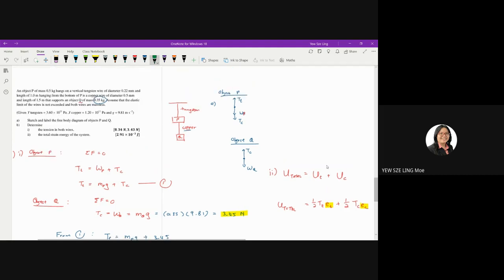Well, for elongations I have two equations. One is epsilon equals e over L naught, and another one is Y equals FL over AE, right? So obviously, I cannot use the first equation because I don't have the strain of the wire. So this one is out, which means I can try to use the Young modulus equation to determine the value of e. So do I have enough information? Well, yes, I do have Y. I'm given the Young modulus. And then I have a force, because I already calculated it in the previous part of the question.